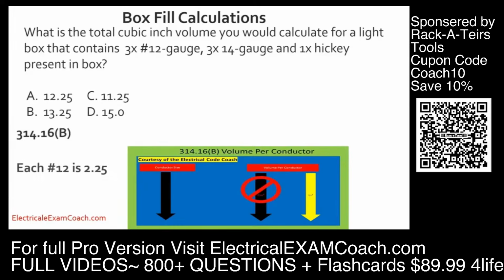We know that each 12 is 2.25. So you always deal with the largest conductors first, and the reason is because your fittings are likely going to be grouped with the largest conductors. We know that we have the 3 number 12s, but now we've got to deal with our fittings. In this case, we have 1 hickey. Each hickey counts as 1 based off the largest conductor that's in the box, and what we're going to do is group it with the 12s.